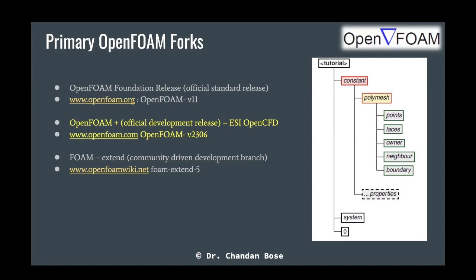Yeah, let's ask from the back. Can anybody tell from the back? To solve an incompressible Navier-Stokes equation, what are the state variables or the field variables of the problem? Louder, please. Okay, correct. So basically pressure, which is a scalar variable, and velocity, which is a vector. And there can be another variable, which can be temperature, for example, if your scalar transport equation involves heat transfer also.